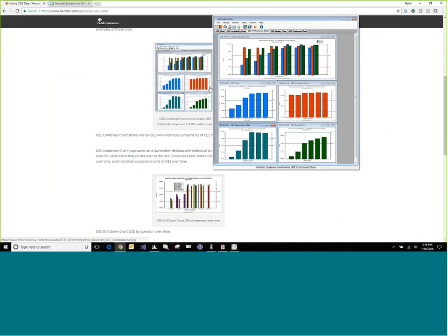Okay. Just a few more things to consider. You might want to look at storing your ideal cycle time in a standard variable, or read it from a table somewhere, or pull it out of another system. You could also hard code the value if it doesn't vary by product or machine, just to make data input simpler so the operators don't have to deal with it. And in order to keep things simple, you might want to ignore planned lunch breaks or other breaks, especially if the machine keeps running during that time. You can always go back and subtract out those breaks later as you fine-tune the data, but to keep things simple, you might just want to ignore those at startup.